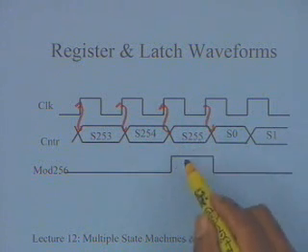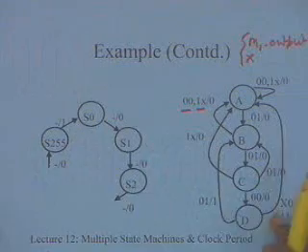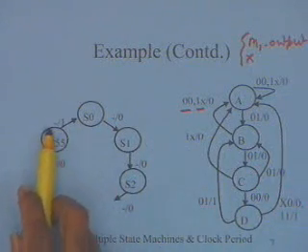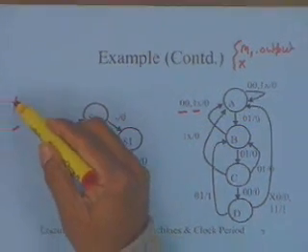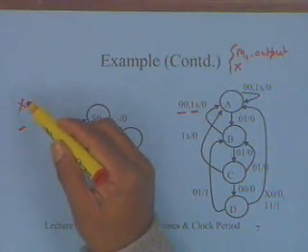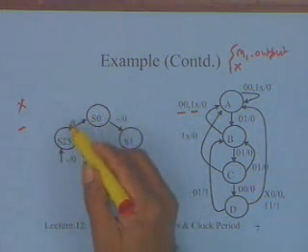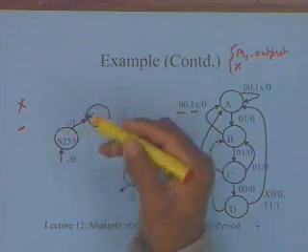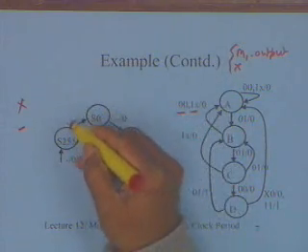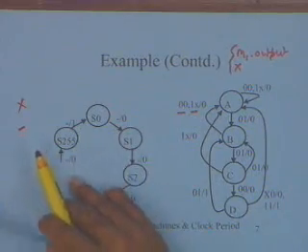Now, if you consider this particular diagram which we had for this state machine, this doesn't have any input. The reason I am using a dash is I am distinguishing between don't care and dash. Don't care implies that there is an input, I don't care whether it is 0 or 1. Dash here I am implying that there is really no input. If I just write 1, it will look like the Moore machine, with only the output specified. That's why I specified a dash. And so there is no input here, it's just going through and generating an output.